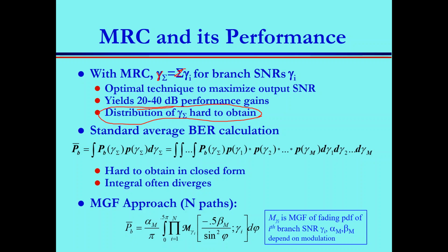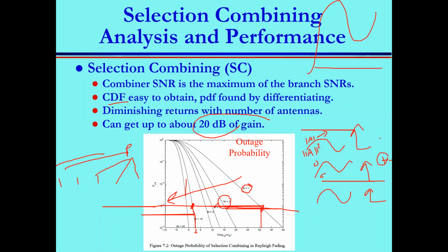Yes, by fitting. For example, I draw my data. Let me explain to you how to get it. You get your channel, yes? Here you have values for the channel. You can even generate it in MATLAB. You build a for loop, and each time you generate 3 Rayleigh vectors, and you sum them.